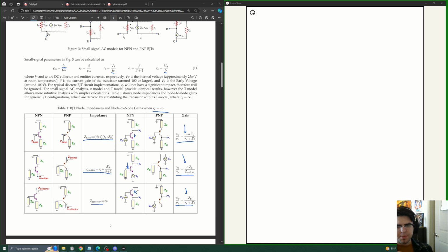So now I'm going to jump ahead just a little bit and look at something that's going to be more useful for Lab 9 or even in ECEN 326 if you take that class. Now that we have all these linear models for the BJT amplifiers, similarly to op amps, where we simply said you have this input and it goes to this output, and that's modeled by the op amp gain just being AV, we can do the exact same thing with these BJT amplifiers now that we have these transfer functions that describe the gain. It makes things much easier.